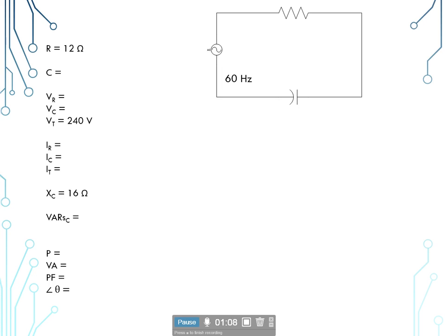With that being said, now the line that runs over the x-axis is always going to be the resistive part of our circuit. The vertical line on the right will always be our reactive part of the circuit, and then the hypotenuse, the longest leg, will always be our total. Now we can use this part of the Pythagorean theorem with our current, with our voltage, with our resistances, or our ohms. Whatever we make the value for one side, the other two sides have to be of the same value for this to work.